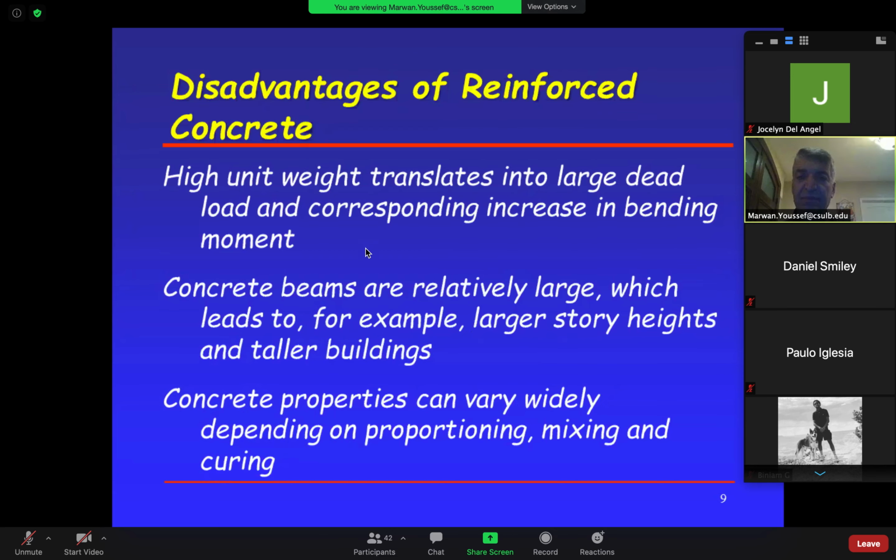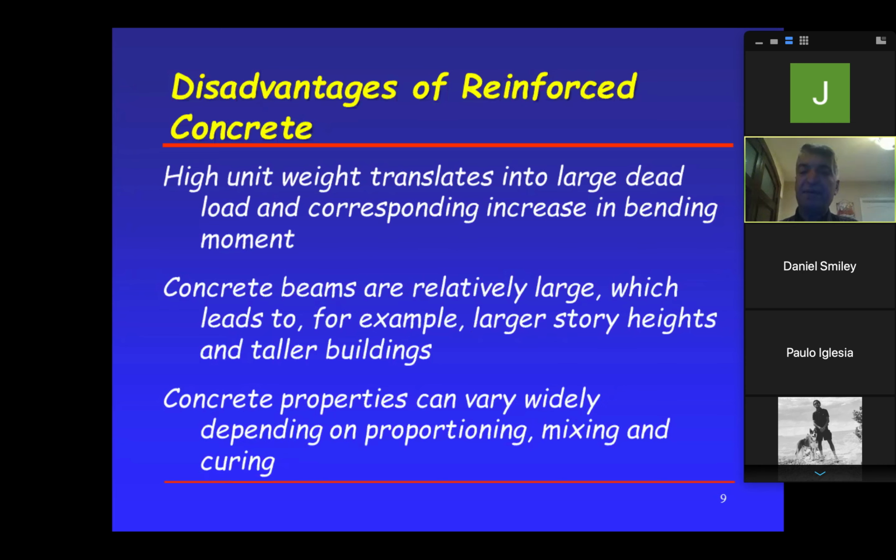If the sun comes up on this concrete we just poured, what's going to happen? Evaporation is going to come up as a result of heat. So that means we're going to lose water from the mix. Well, that water we counted on to be for the chemical reaction, right? So our chemical reaction is not going to be as we designed. That's why we put water on top, so that if anything is going to evaporate, it's the water we just put in, and the internal water remains. Okay, that's one thing.